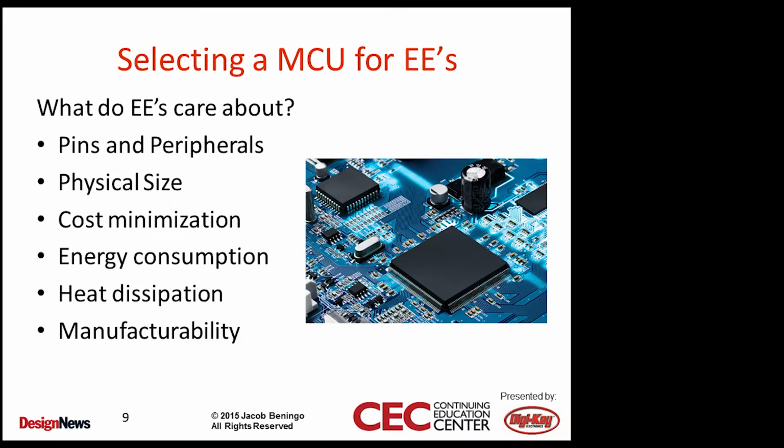So what are some of the things that electrical engineers care about when they're trying to select a microcontroller? Now, when you think about it from an electrical standpoint, an electrical engineer cares about hardware. He cares about the physical package size of the microcontroller. He's going to be looking at, okay, how much room do I have on my circuit board? How much solder is there going to be? If you have a BGA type component with the pins on the bottom, that's going to have some structural issues perhaps when you're going to develop your PCB layout, maybe the way that the solder attaches, the way it goes through reflow. Electrical engineers are going to be thinking about those types of things.